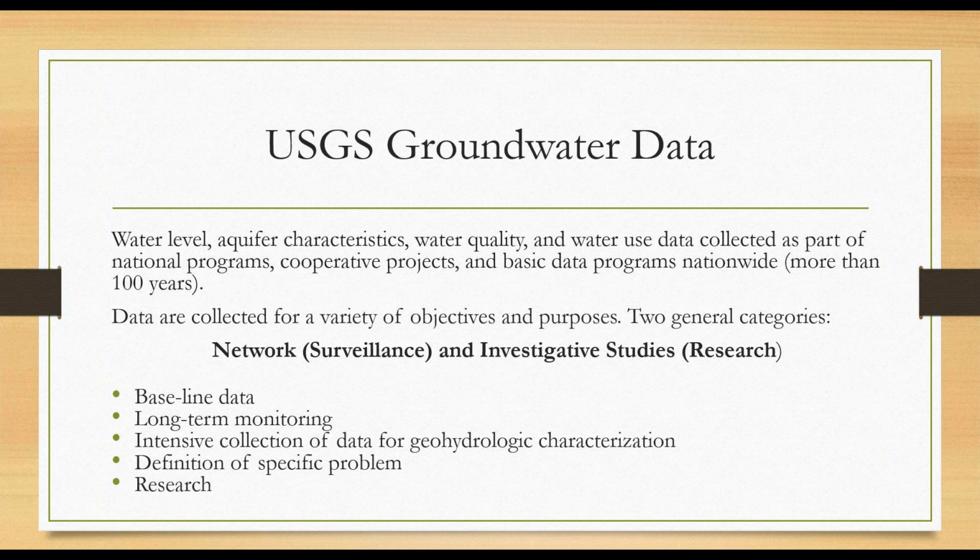Within those categories, there is baseline data. Baseline data, what we mean by that is we get information for determining the future changes from the initial or baseline conditions. The baseline data establishes a benchmark for future investigations. There's also long-term monitoring. Long-term monitoring looks at temporal trends or changes over time, and are often needed for calibration of groundwater models and things like that.